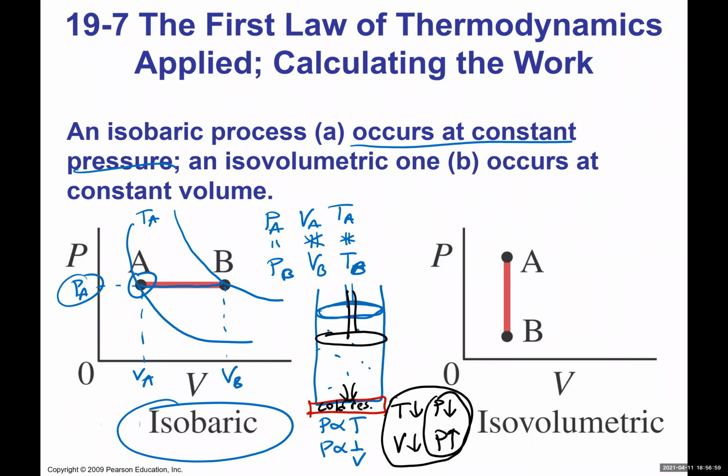If you do it in such a way that they're proportional, that means how much you change the pressure due to the compression is exactly the same as how much you remove heat and decrease the pressure. You can see that if you add those changes together, you're going to get no change. That means how much you decrease one way plus how much you increase the other way, the changes cancel each other and you have constant pressure. So that's how the isobaric process works.